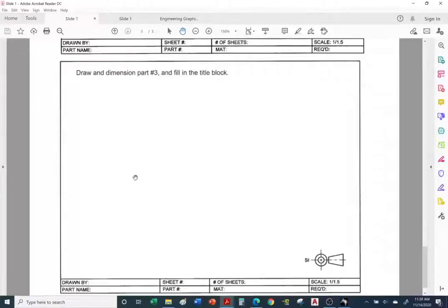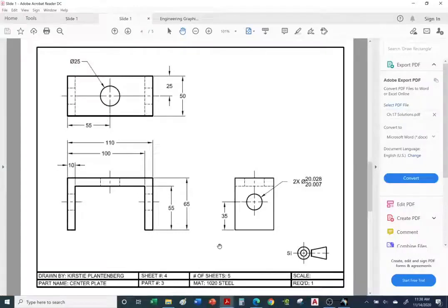If your lines are all over the place, crooked, or not exactly horizontal or vertical, it's okay. I'm not going to take points off. I just want to see your drawings complete. This is what it's going to look like. Your front view: don't forget your hidden lines, center lines. Again, don't forget your hidden lines. So complete your front view, top view, side view, and don't forget to dimension. And once again, don't forget to call out the diameters of the holes. That's the one thing students forget.